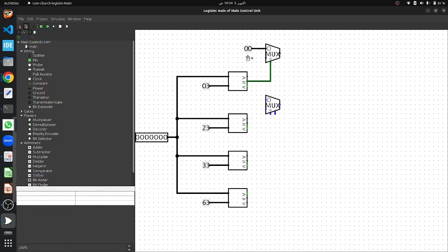And the second input of my mux will be 0, 1. You can say, right here, using this mux to select my control signal for the next logic I'm going to design here. So either it will select the 0 input, or it will select the 1 input, right? So let's make multiple copies here for each and every comparator.